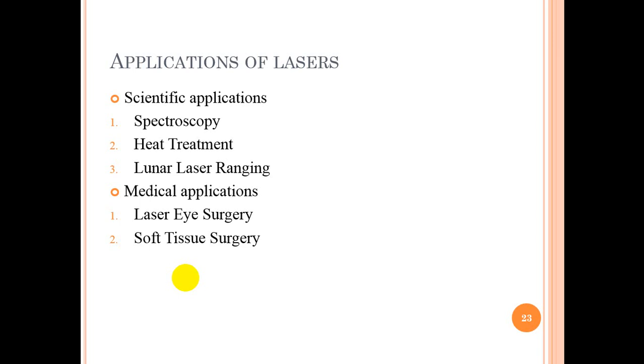Number two, heat treatment. Heat treatment with lasers allows selective surface hardening against wear with little or no distortion of the component. Because this eliminates much of the machining that is currently done, the laser's capital cost is recovered in a short time.